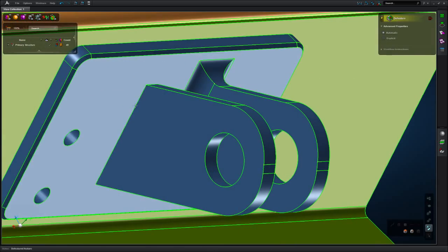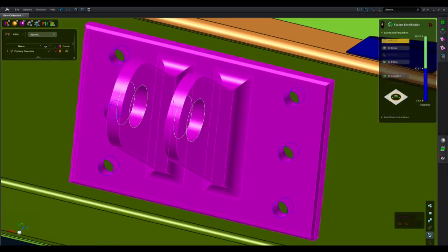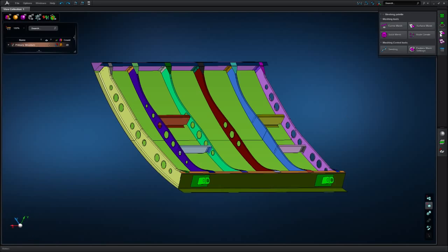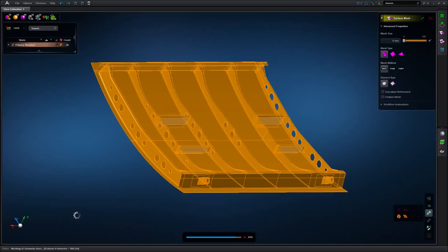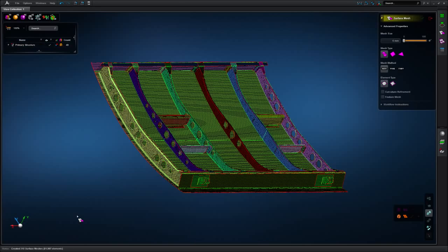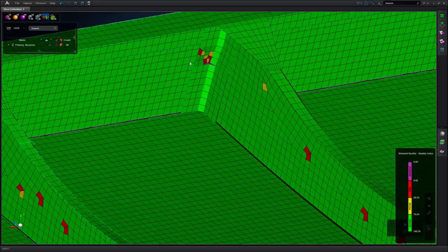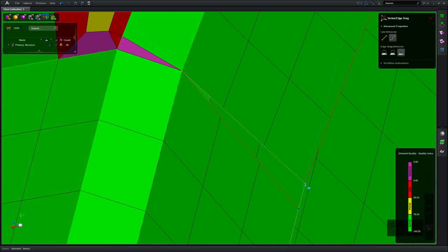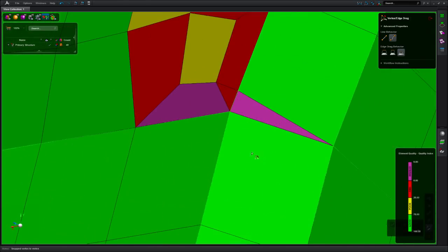The particular tool can be used in the point and execute manner, or I can select numerous features to remove at once. Let's go ahead and mesh this model. A look at the mesh quality reveals some poorly shaped elements. No worries, I'll simply select on the geometry and move it until the quality of the mesh is improved.